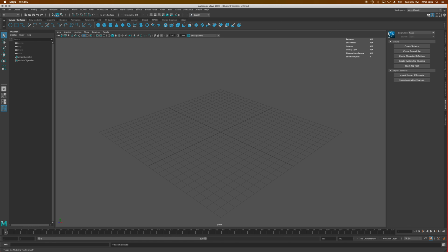Also, we want to make sure your workspace is probably in the classic workspace instead of standard. The reason why is we want to see your timeline, because to make your dynamic systems work, you have to be able to start using the timeline. You don't necessarily need to animate any of this. You can still take stills from it, and I'm going to show you how to freeze one of these effects transformations and then be able to render it. But you still want to let the dynamic system run, and to do that we need access to the timeline. So workspace on Maya Classic, and your menu system on FX.